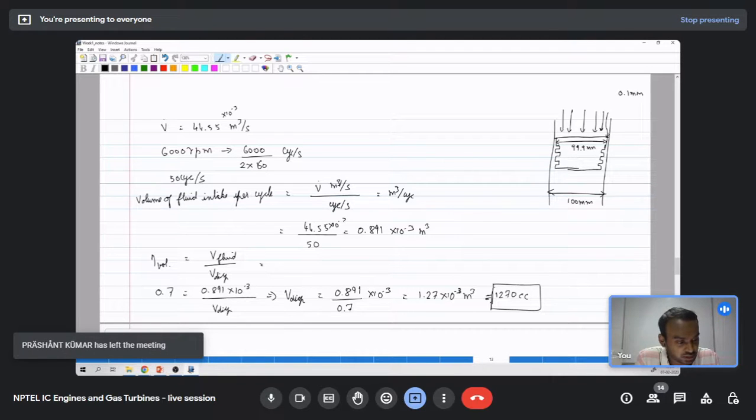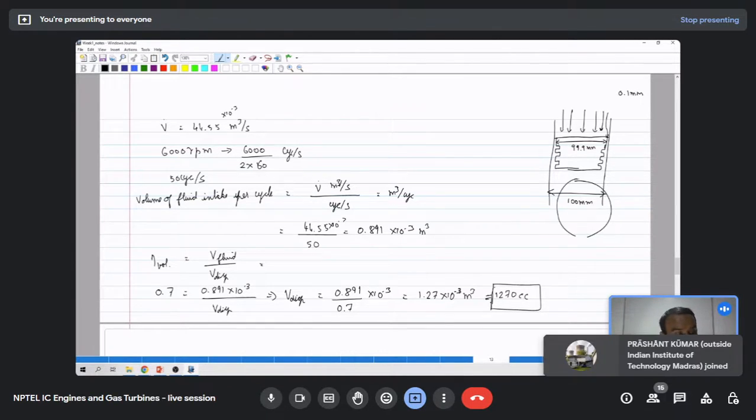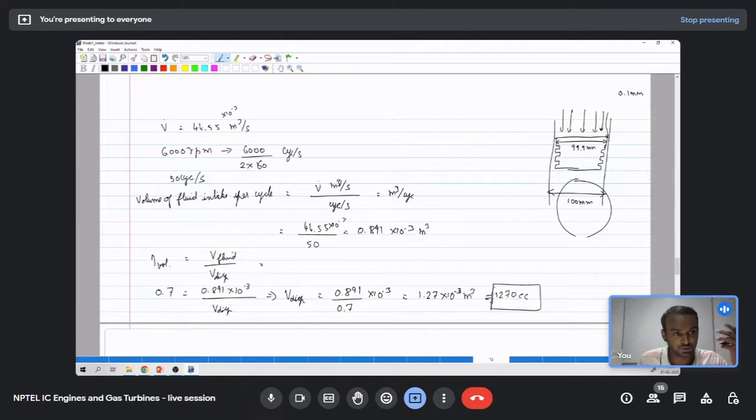the gas can flow through this, and whenever we compress, some gas passes through the piston and comes to the crankcase. This region is called the crankcase, where the crankshaft is located. Because of this, we will lose much energy during compression and expansion. In order to avoid that, we need a mechanism, which is achieved through a piston ring, fitted by compression. A piston ring has a notch or opening on one side. It is not a full circle, it will always be open.